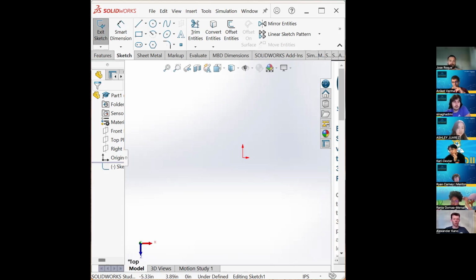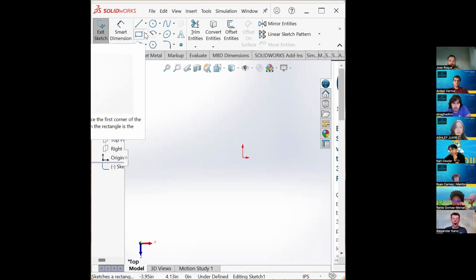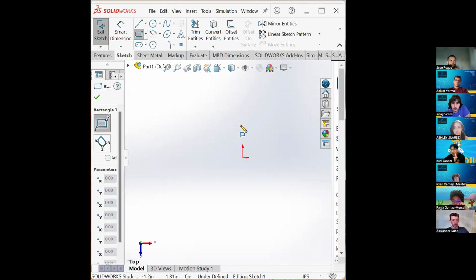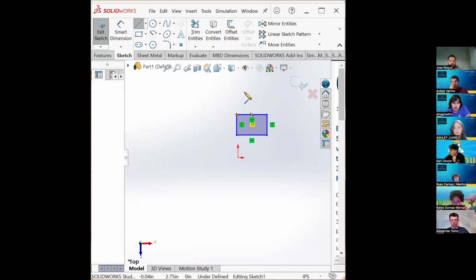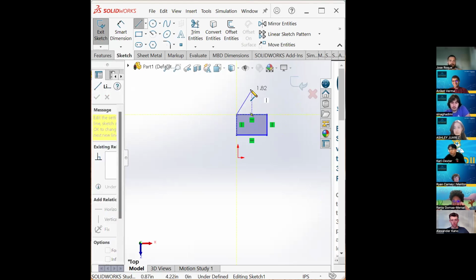So I'm noticing immediately my simple geometries. I'm noticing rectangles. I'm noticing a triangle. I'm noticing circles. So I kind of have an idea how this is going to go. So I'm actually going to click my corner rectangle. I'm going to click it just in an arbitrary place in space because I want to show you the importance of the origin later. I'm noticing this triangle, so I'm going to go corner to corner. Notice the dashed line. I'm going to explain that in a bit. Click here and then click to the bottom.